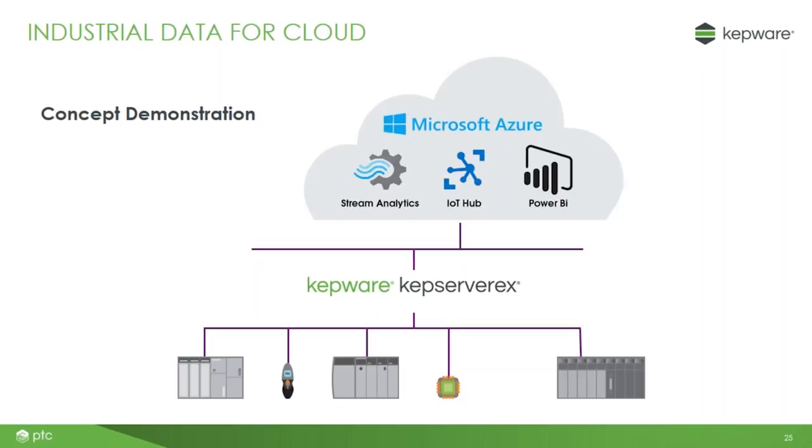So in all of our examples today, we talked about the use of the IoT Gateway. Just for folks who are unfamiliar, again, the IoT Gateway is a plugin for KepServer. And you can think of KepServer as having 3 layers, right? It has the driver layer, our southbound interfaces, we could say, where we're connecting to typically process control equipment, sensor technologies, databases, other software applications. We can integrate with third-party drivers through a number of tools. We have tools to graphically develop your own protocol drivers. So that's all our southbound stuff.